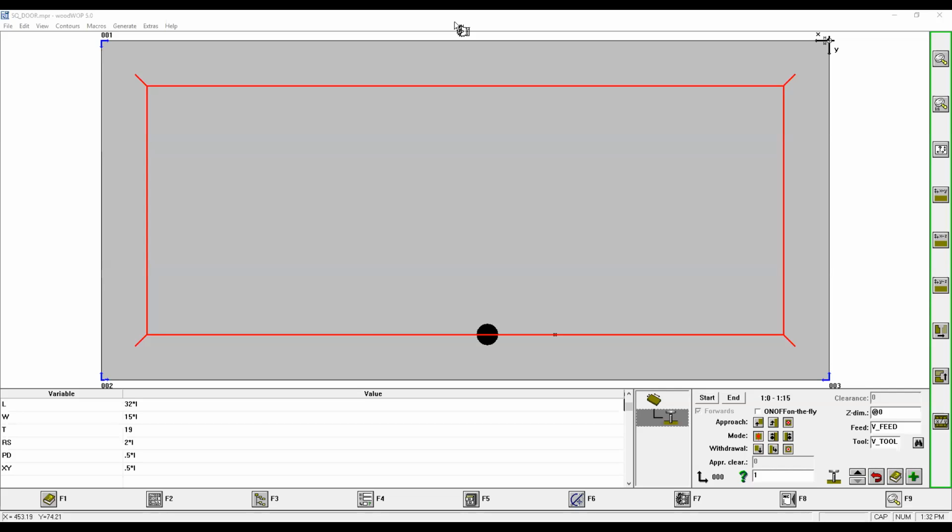One of the applications that 7 does give us is that we have the ability to draw a contour on the vertical surface and do an arc there, a true radius, and then put a vertical tool on that. That really came out with the version in woodWOP 7. But if you have more questions specifically about 7, please reach out to us. We can help you out with that.